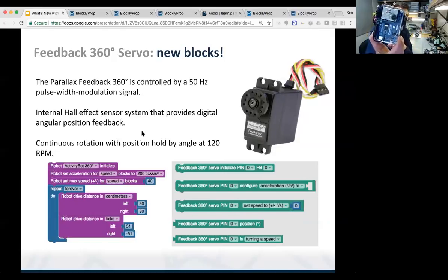And to give you an idea of the importance of encoders in robots, there are fewer educational robots that have encoders than you'd imagine, but they're absolutely necessary for anything where you're doing distance equals rate times time, okay? So you have to have a distance component to have a useful robot servo, and that's for something called dead reckoning, where you want to just travel a certain distance before you do something in particular.